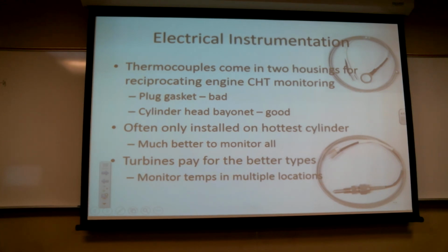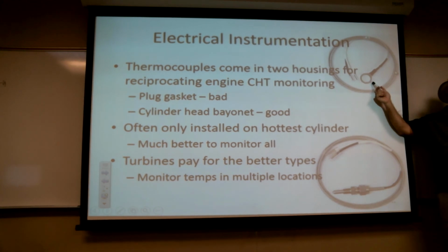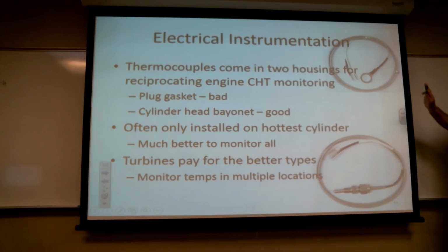Remember the spark plug gasket that you were supposed to replace every time you pull the plug out? But apparently not with this, I don't know. Remember the spark plug is designed to control the heating and cooling of the cylinder head? So a lot of extra heat leaves through the spark plug. So this might actually not be the temperature of the cylinder head. It's probably going to be quite a bit hotter. I do not recommend using these. Garbage, garbage, garbage.